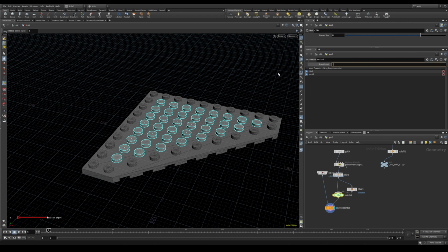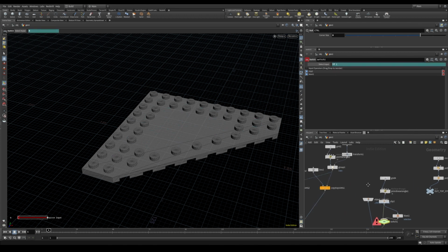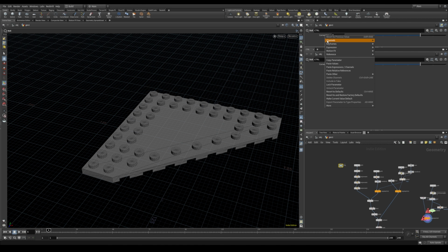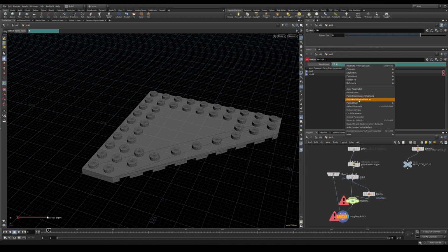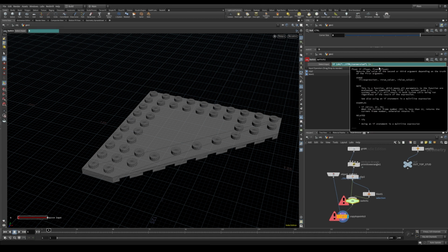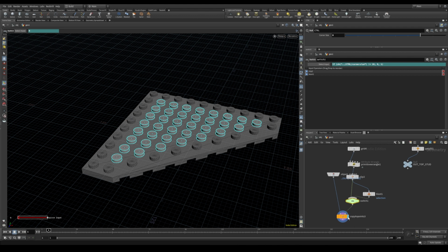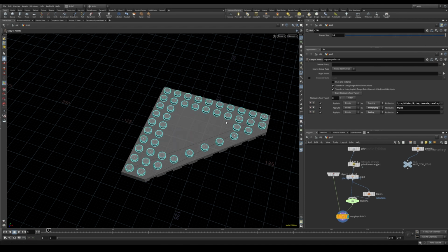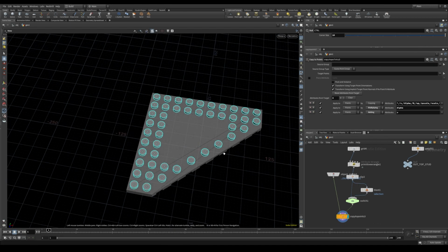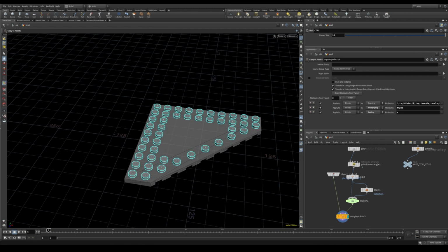So we can write that if, let's take the corner sides, copy parameter. So if the corner sides past relative reference is different from 10, then take the first input, otherwise take the second input. So now we should have every stud except on the 10, which will switch to the blast node. So we're done with the top stud also.